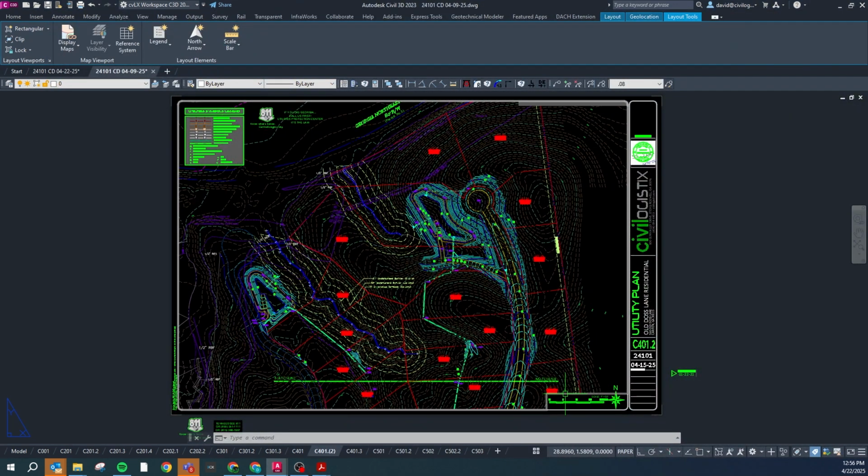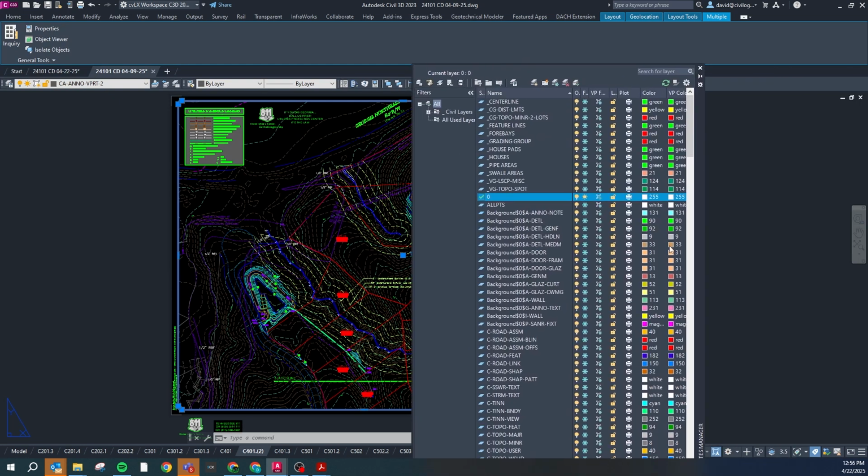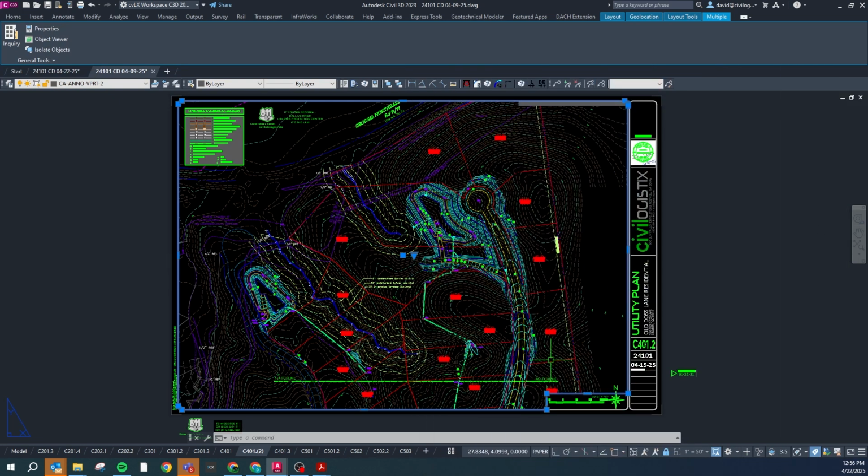We have a command called VP match, and when you do VP match, it's going to set every viewport on that same layer to match the width, the height, and the scale. It's important that the viewport sizes go edge to edge and top to bottom, because the way the command functions is it takes the center point of the viewport area and locates that at a certain space in model space, and then it does a certain zoom. So if we move this side over, the center is going to be over here, and so it's going to be in a different location.